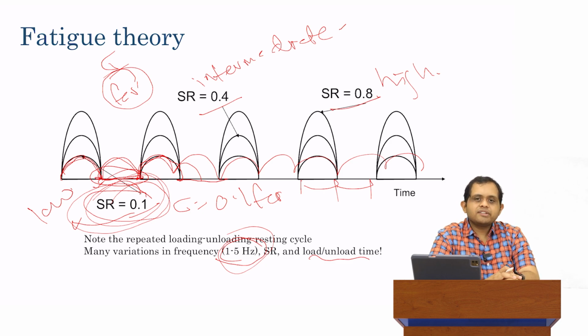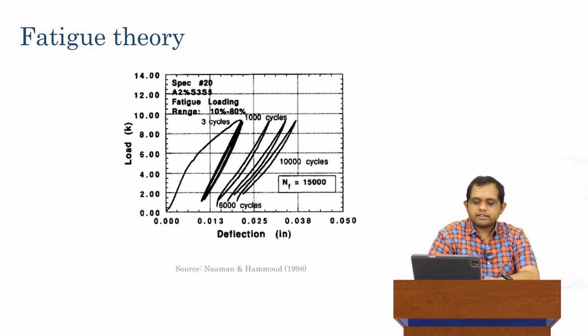To conduct it, you also need somewhat specialized equipment. You need a UTM which is capable of cyclical loading. But it is a more complicated test because we have a couple more parameters of the test that we get to choose, and the results then vary depending on what those parameters are. So just keep that in mind. The test can get somewhat complicated, depending on how exactly you're running the test.